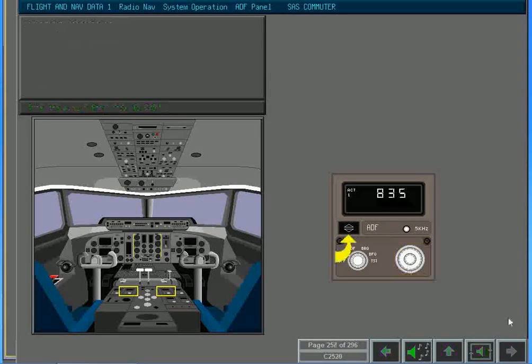When the active frequency has been tuned, the standby frequency can be restored by pressing the frequency transfer button for another 2 seconds. Tuning of the standby frequency is once again available. The ADF system is inoperative if a fail message is displayed in the frequency display window. If no signals are received from the tuned station, dashes appear in the lower display field.